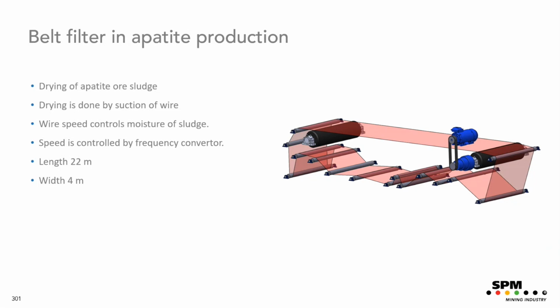What is special with these ones is that there is a lot of moisture and low RPM. And it's not only low RPM, the RPM is fluctuating as well. So typically during a data acquisition, the RPM can fluctuate 1, 2, 3 RPMs. And that is quite a lot considering the relation between the RPM and the fluctuations. So the percentage RPM fluctuation is relatively large.